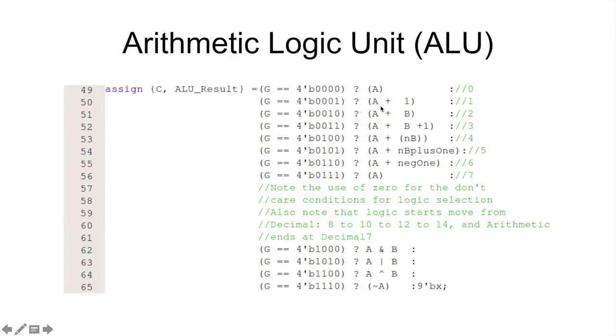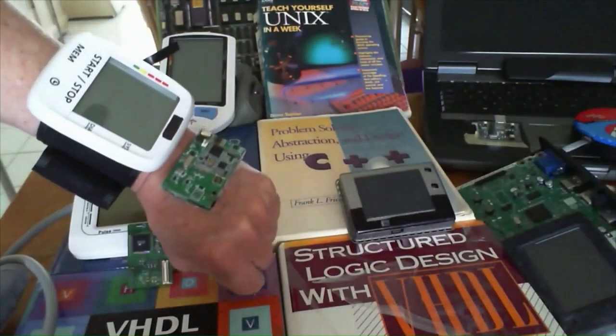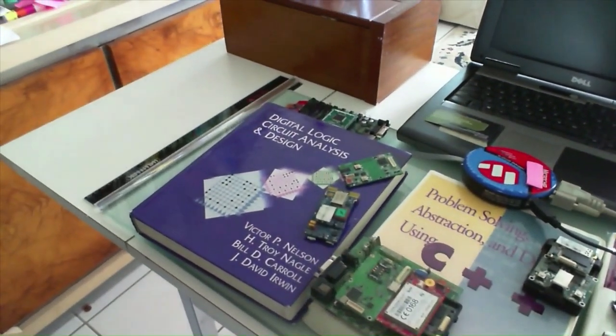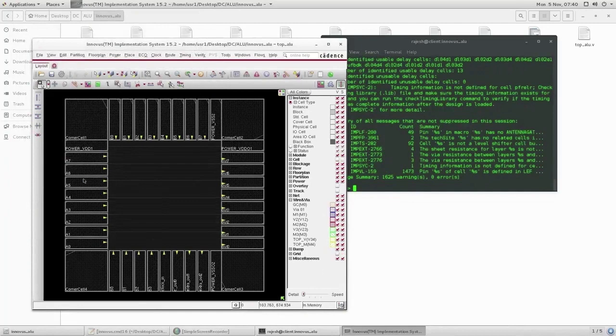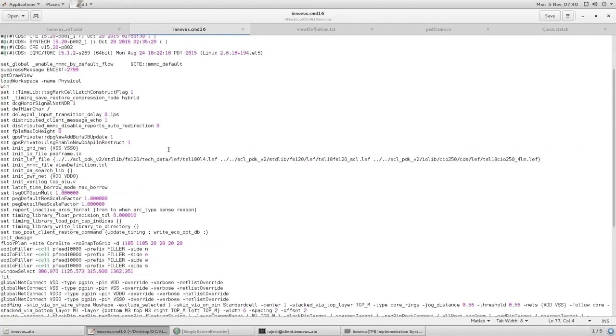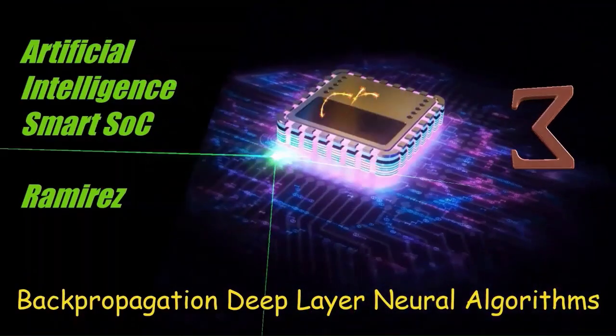So we want to fine-tune the wires for some nets, such as clocks, and keep these wires fixed through multiple passes of engineering changes. At the end of routing, all new wire segments are assigned to a user-specified group. The routing program makes sure that nets routed in one iteration do not prevent the remaining nets from being completed.